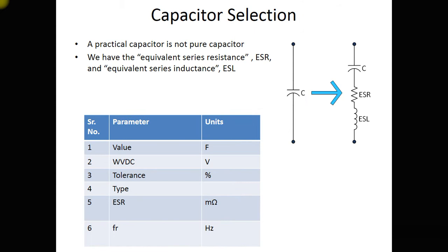SMPS designs. Capacitor also is a very important component over here, and this is not the capacitor that we normally use in the linear power supply, because at higher frequencies the model of the capacitor is not purely capacitive. It has some equivalent series resistance and equivalent series inductance also associated with it.